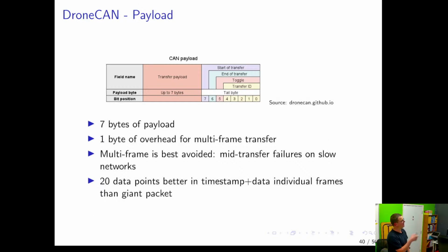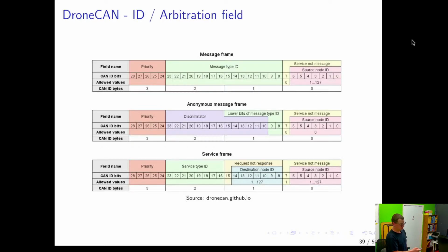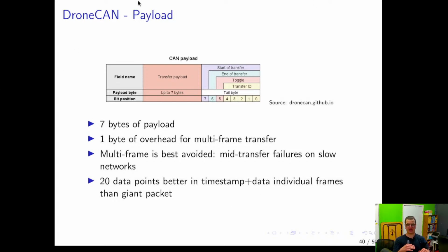Oh, I see what you're asking. The GPS node will have some number here, but the way you would know it's a GPS is because the message ID would say something like GPS fix message, UAVCAN.GPS fix message, and it will have the data in it. So the device doesn't matter necessarily, it's the message it's sending out. In a car, maybe the CAN bus ID is like a sensor ID, but in DroneCAN, the ID field is filled with the message type, basically.